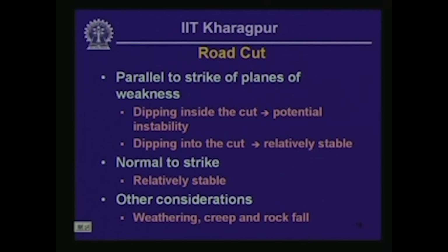There are other considerations such as weathering of bedrock. Because of the road cut, you might give pathways for water entry through the joints and planes of weaknesses into the rock mass, that might trigger chemical weathering. Creep is another issue that needs to be accounted for during construction of a road cut, as well as the possibility of falling rock from the top of the road cut.